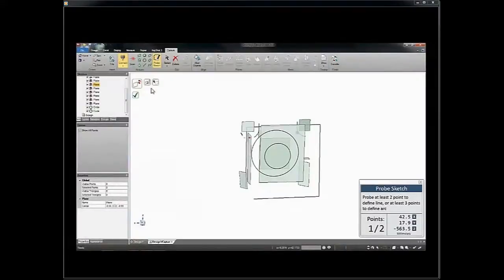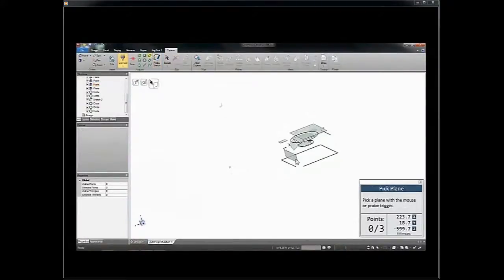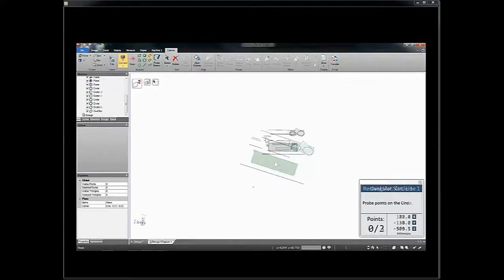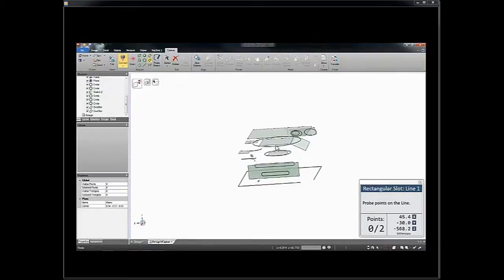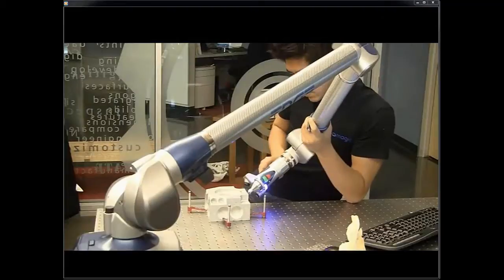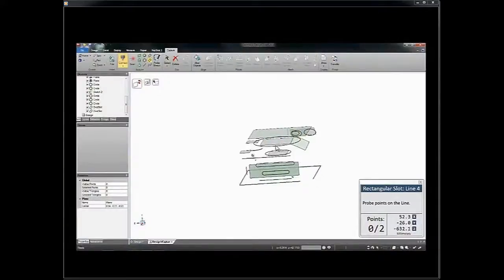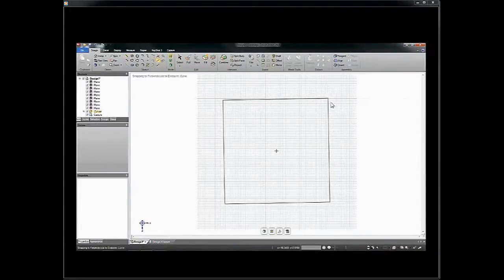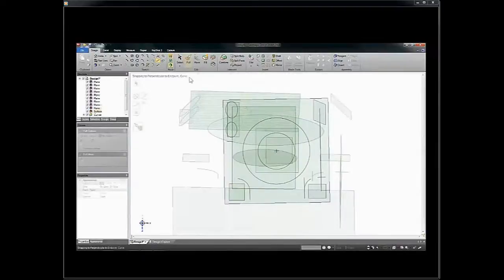He's creating that little U-shaped channel. And there's connectivity between the entities. So as you go from one entity to the next, you can choose whether it's a tangent connection or a non-tangent connection. There's also inherent smart snapping, where it will snap to existing X, Y, and Z coordinates. It also tries to maintain parallel and perpendicular relationships. So it's more than just creating lines in a free-form fashion. There's a lot of engineering thought given to this, knowing that people will be creating a lot of concentric, parallel, and perpendicular shapes.